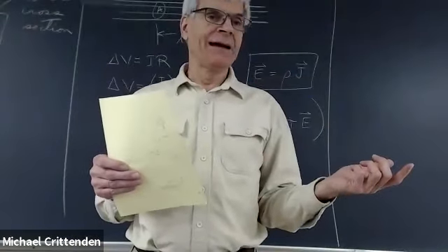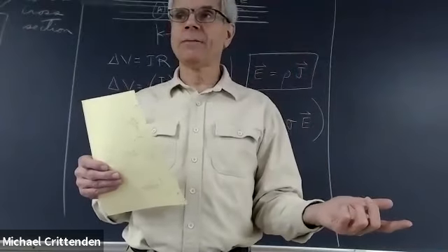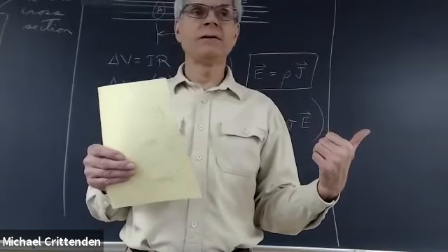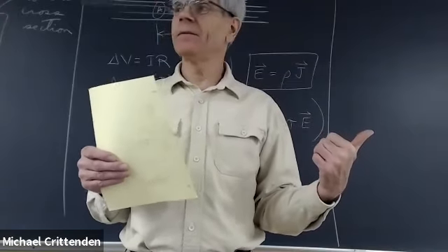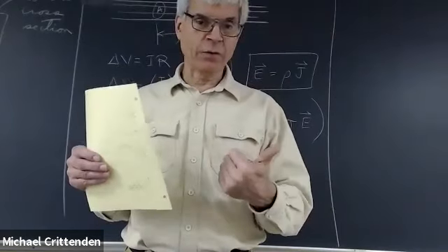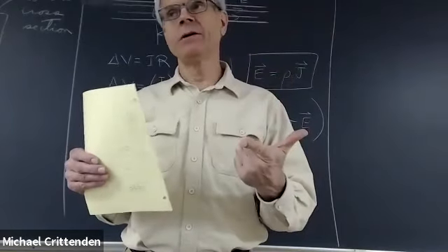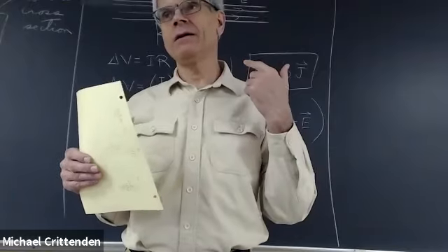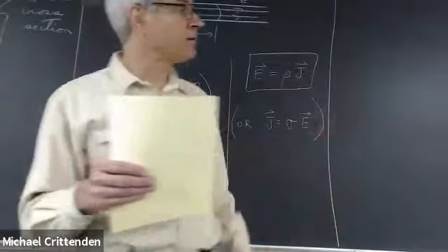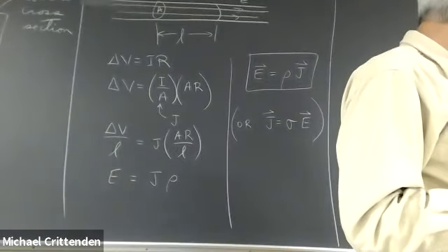As we'll see in a few minutes when I get started into section 5, the power used by a resistor is equal to V squared over R. So if you know how many watts you want to make the toast in a proper amount of time, and you know you're plugging it into 120 volts, you can calculate how many ohms your heating element ought to have to produce that number of watts. And in this case, that turns out to be 24.